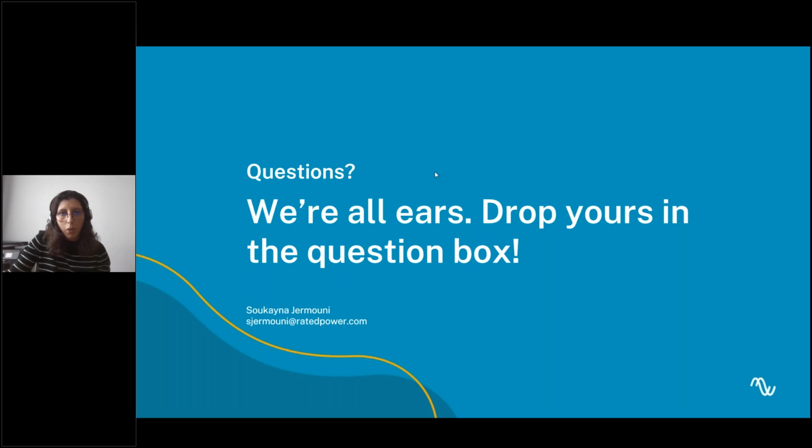We'll wait for questions. Give it a second. Okay, first question is about the power factor in the AC BESS. If we consider the capacitor bank a strategy for that to compensate for the reactive power, meaning yes, we do. For both the inverter or the reactive power in the PV plant or the battery system can be compensated using the capacitor bank in the same tool. So it's a yes, you can actually size the capacitor bank for both to compensate the reactive power of both systems.